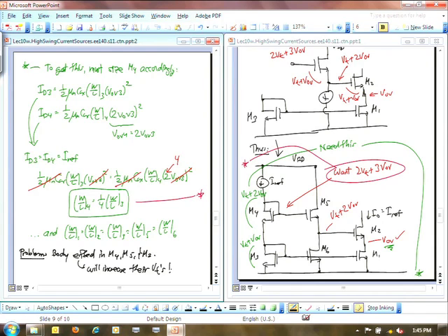Okay, so let's start looking at this in a little bit of detail. First of all, I know that VT4 is not going to be equal to VT5. The VT of M5 here is going to be approximately a VT of 2 plus 2 times the overdrive voltage here. And which is the bigger voltage that we're looking at? Obviously, 5 has the bigger voltage.